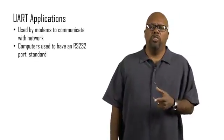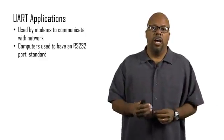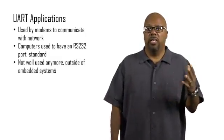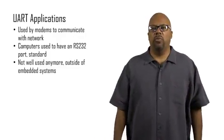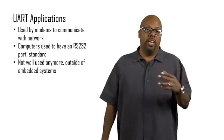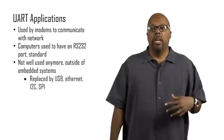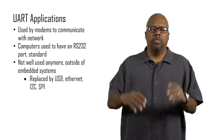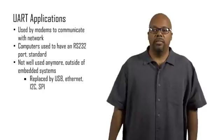Computers used to have an RS-232 port as standard. RS-232 is a port made to communicate with UART. They don't do that anymore because UART has been supplanted by other, better, more effective protocols. So it's not well used outside of embedded systems and IoT devices like we're dealing with. It's still used in those domains, mostly for debugging. But it's been replaced by things like USB, Ethernet connections, I2C, SPI. We'll cover those later. There are a lot of other options you can use instead of UART nowadays.